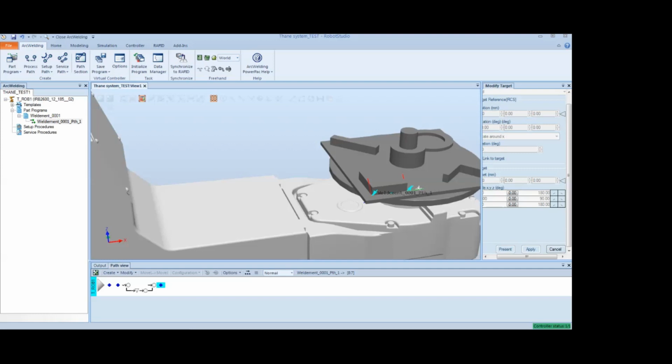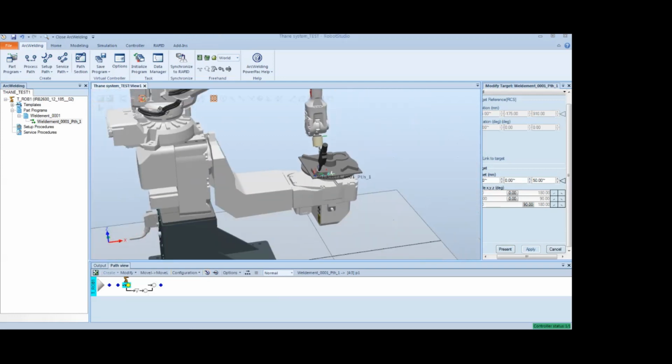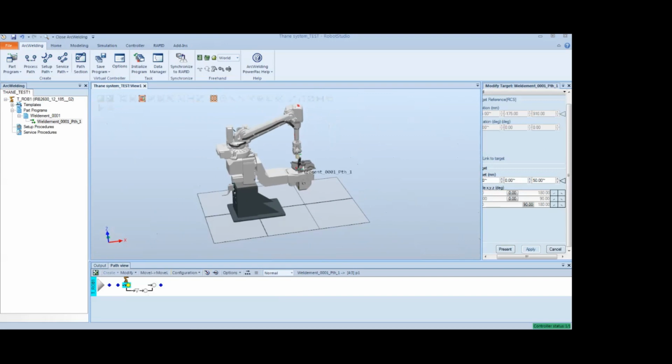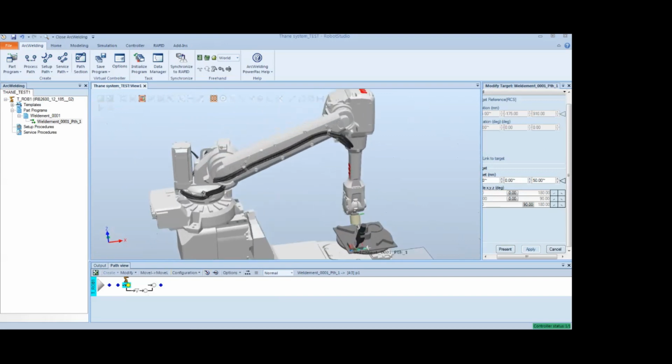To do this, you select the targets you want and then click jump to or move on the commands. So we'll do the jump through option first. We'll select the first point and hit jump to, and the robot TCP is going to jump to that point. If it can't jump to it, it's going to say that it can't. Right now, it looks like it can make it. There's no joints that are overly stressed right now, so that looks okay.